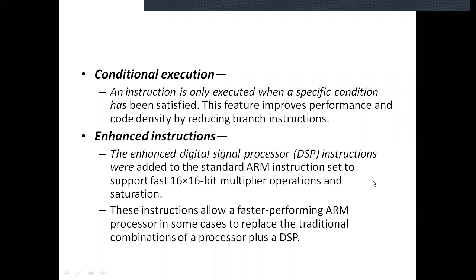So another thing is that they have an enhanced instruction set. Enhanced digital signal processing instructions were added to the standard ARM instruction set to support fast 16x16-bit multiplier operations and saturation. So these instructions allow faster performance ARM processors in some cases to replace the traditional combination of a processor plus a DSP processor. So they have added additional instructions to the basic ARM processor instruction set, so that you can perform digital signal processing operations on the